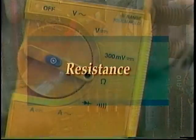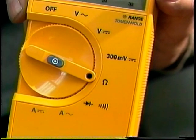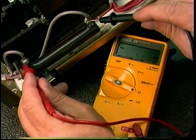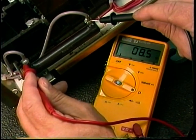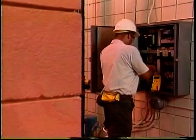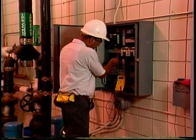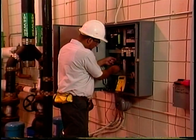Resistance. Resistance readings are taken to determine the condition of a component or a non-powered circuit. Resistance can range from 0 ohms to infinity. Based on the expected reading of the component tested, one of two different meter settings can be used.